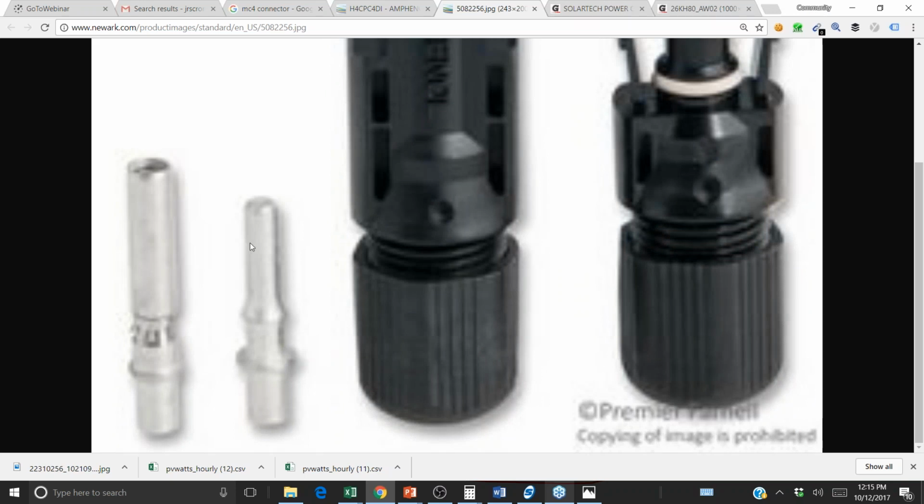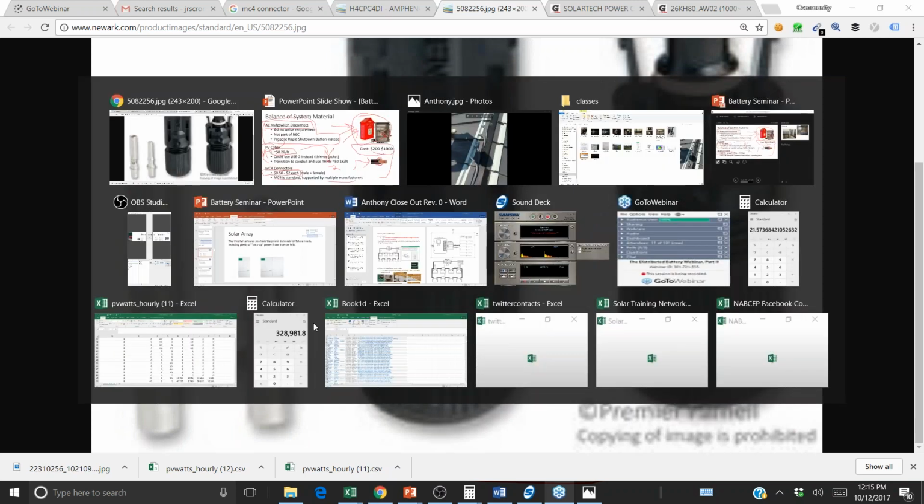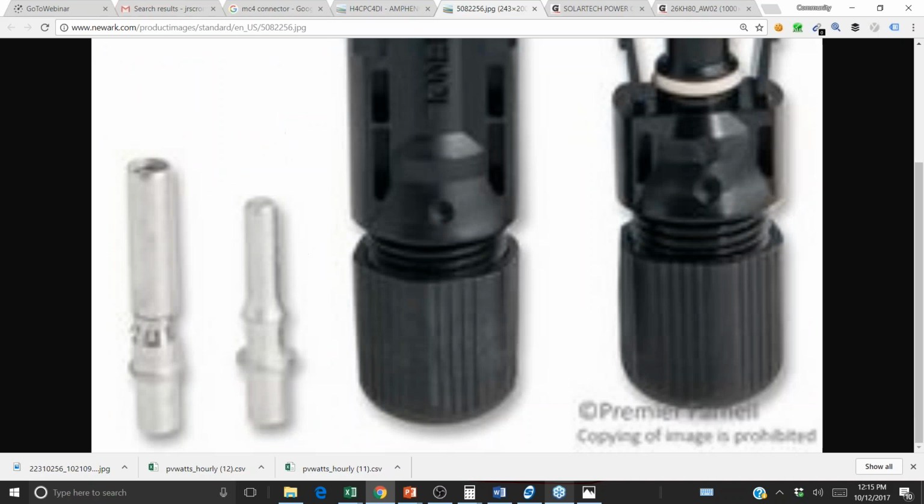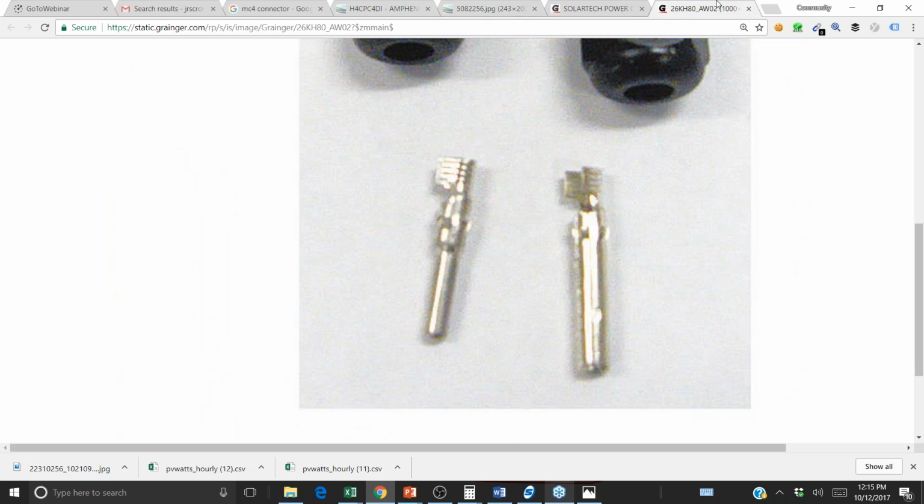In my experience, I found that these kinds of MC4 connectors are less likely to slip. So that's really an install issue. That's not anything that a do-it-yourselfer would pick up on, but in the field, when you're buying your MC4 connectors, I like the ones that have the full housing around the actual copper, and not the ones with this little half cylinder crimp connection that's a little bit weaker.